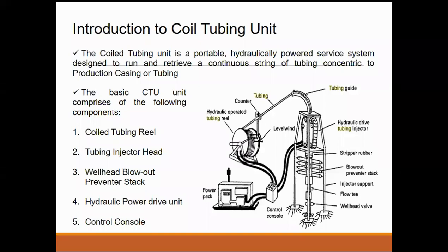So for making those cuts, for making those holes, a special BHA, a bottom hole assembly, is used. The bottom hole assembly is used for sand jetting perforations. It has small tools with small nozzles which have really small diameter, like 0.18 inches or something.